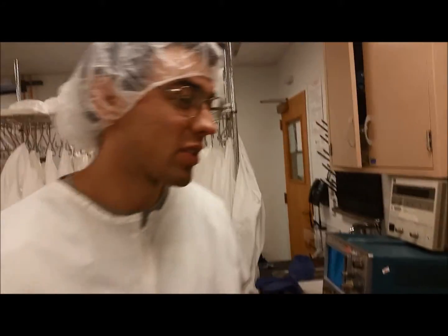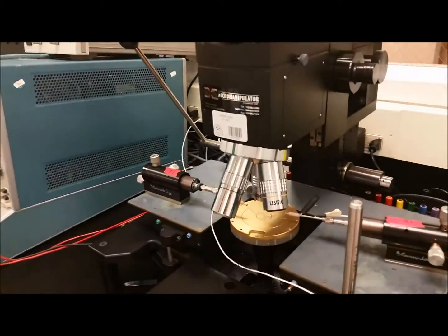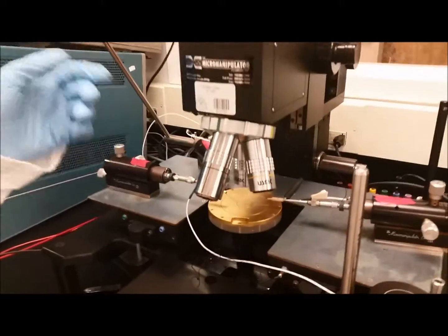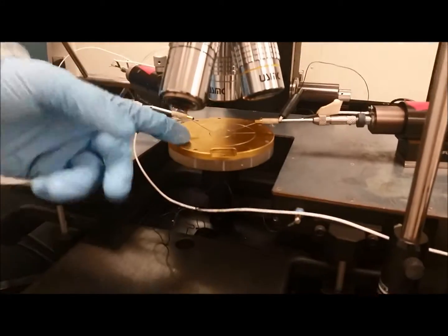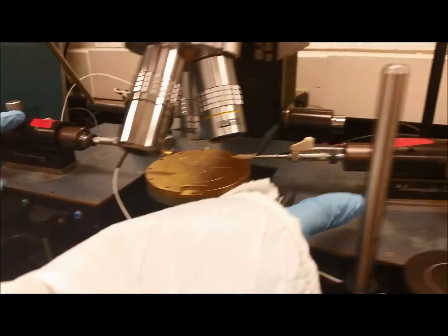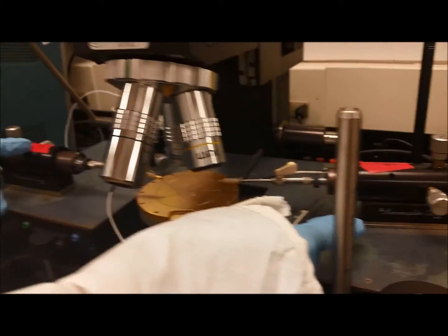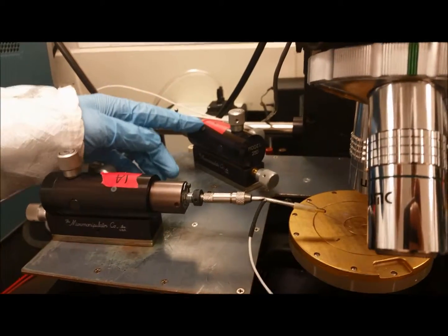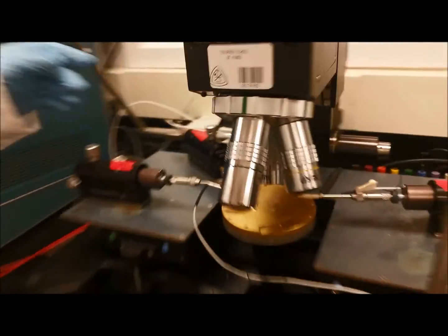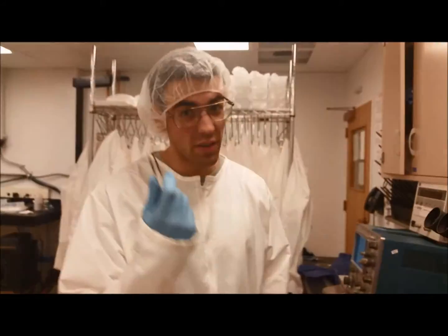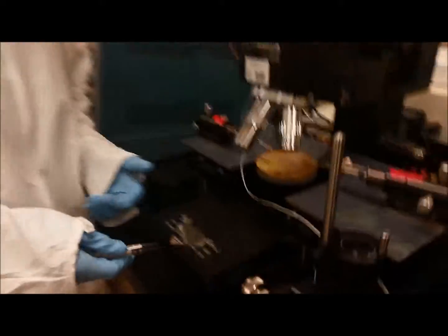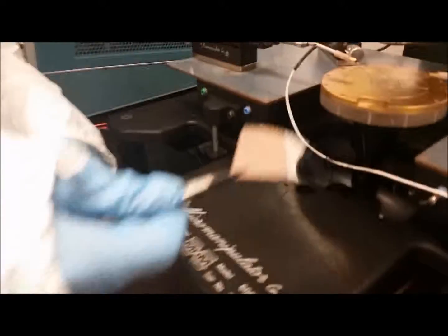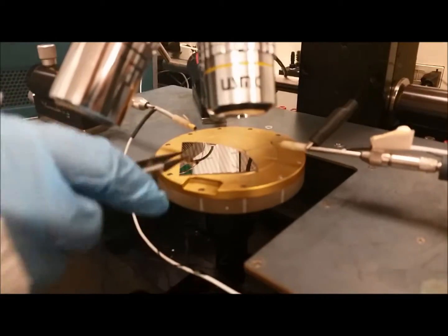To do that, go to your optical microscope. Underneath it, there is a conducting base plate, and two probes that you will actually be using, and a third probe that you could theoretically use for 3-terminal devices. So to start out, take your tweezers and your sample and load it onto the base plate.